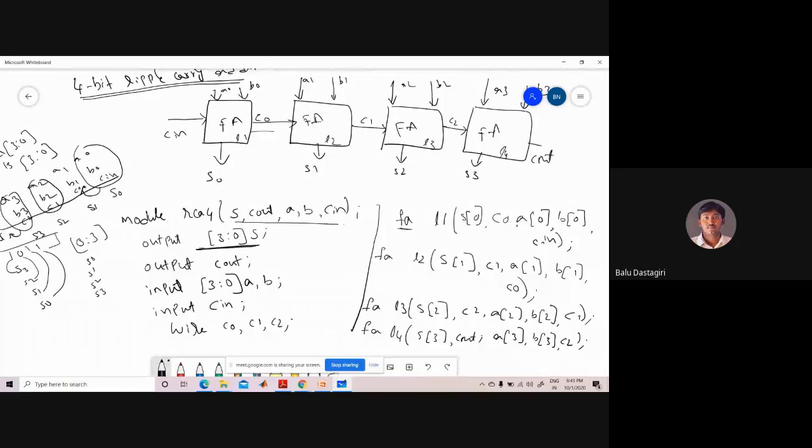Now we have described all the blocks present in the circuit as well as their interconnections. Therefore, write endmodule. So now I am writing endmodule here. This is how you can specify a given architecture by using module and module instantiation. This is also referred to as the structural style of designing the program.